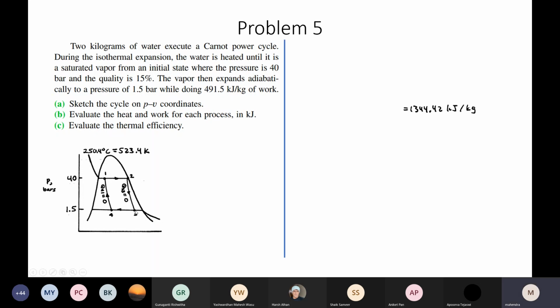Then the condenser is connected. Phase change happens over here, and then a certain dryness fraction is involved, liquid phase as well as vapor phase. Then that is pumped back to the boiler. The problems with the Carnot cycle, we will be discussing when we discuss the Rankine power cycle particularly.